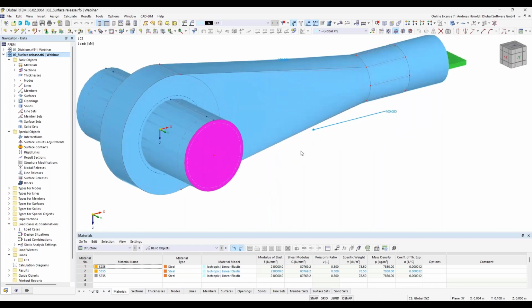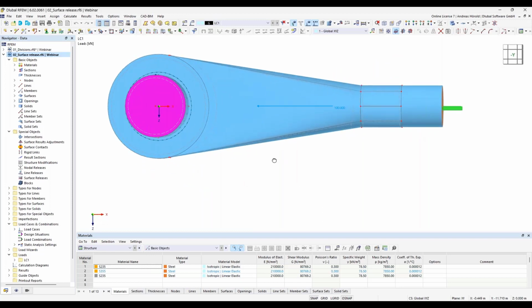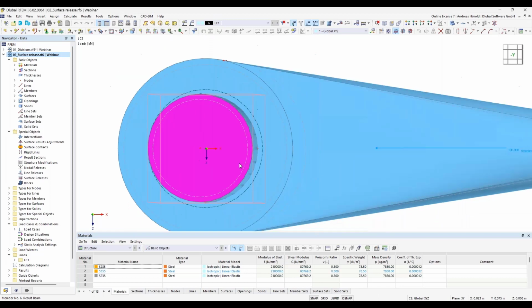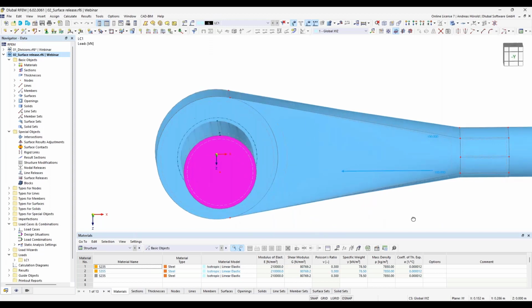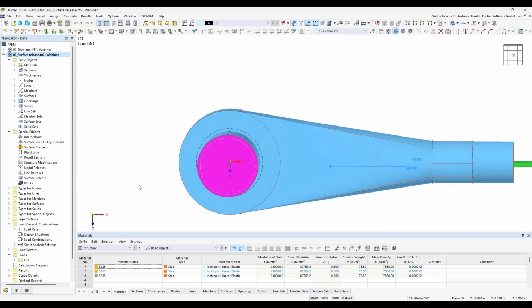This example shows a grommet and through it a bolt is put in that place. The contact conditions in this area should be defined so that the surfaces under tension can detach from each other. So if I load the bolt here, as we defined, it should be released on that edge here. So how to do that?